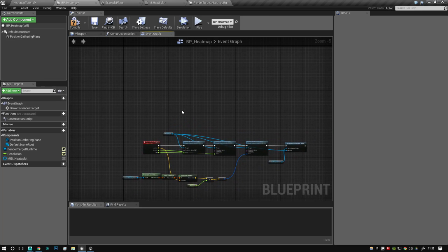So we could now just grab the player character's X and Y from the world straight away, but I'm going to go a slightly more complicated route, and it is more costly, but really I think it's worth it, where we're going to do a multi line trace from the plane to the player, so that way we can create custom bounds if we needed to exclude locations from the heat map, rather than always finding the position of the player in the...